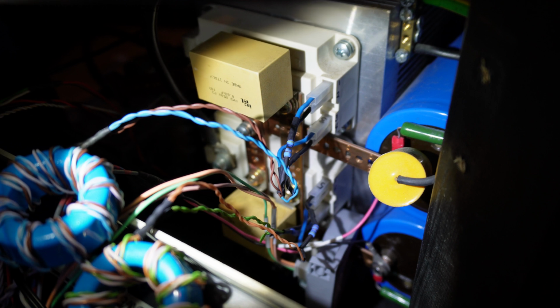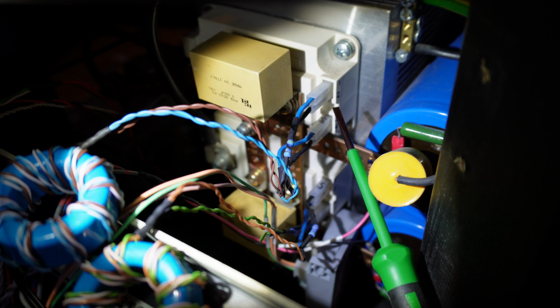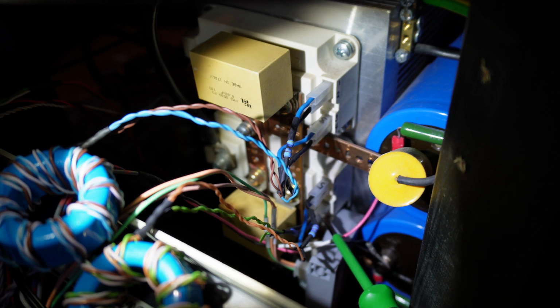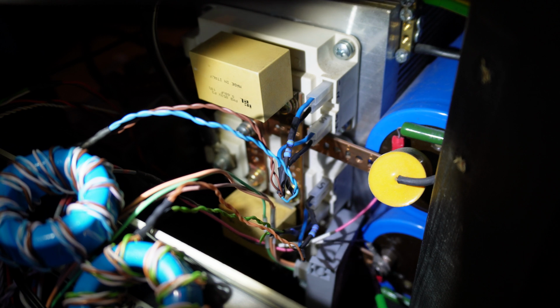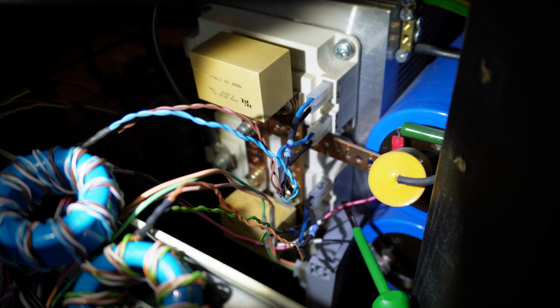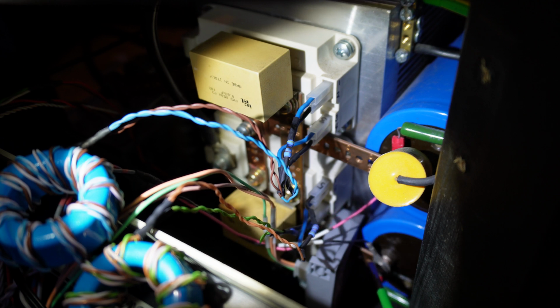It is a little cramped down here at the inverter, but I have my 4 gate connections here on the IGBT bricks. The pink and black wire sitting over here is the DC bus measurement. They have put in series 700k ohm resistors, so it can sense a maximum of 700 volt DC. That's 100k per 100 volt as per the documentation. And as I'm running rectified 400 volt AC, that is around 560, so that fits very well.